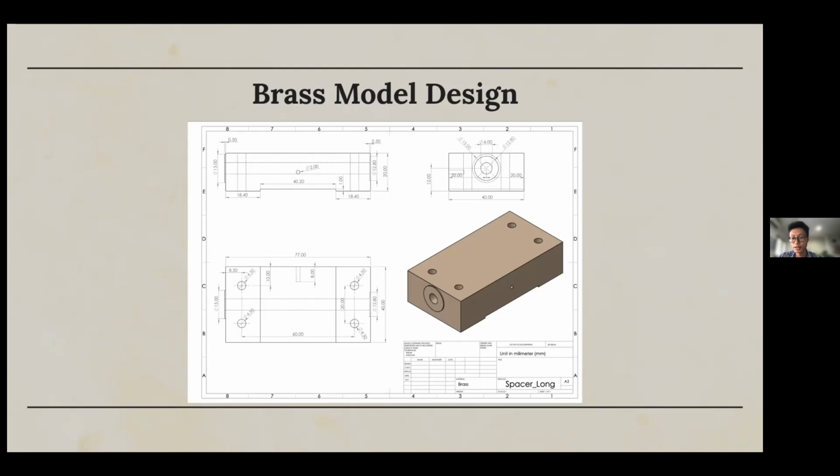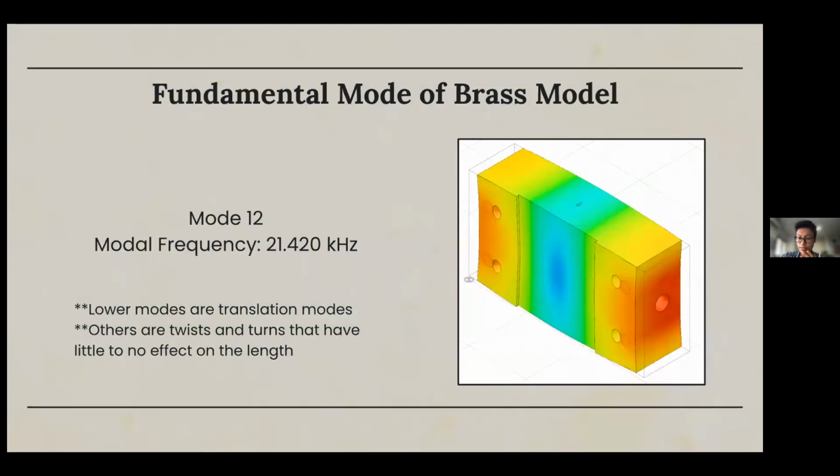The modal frequency study that we conducted covered approximately 80 modal frequencies, but I will be focusing on the fundamental mode as it is the most significant to the cavity's deformation. So in its fundamental mode, we have a modal frequency of 21.40 kilohertz.